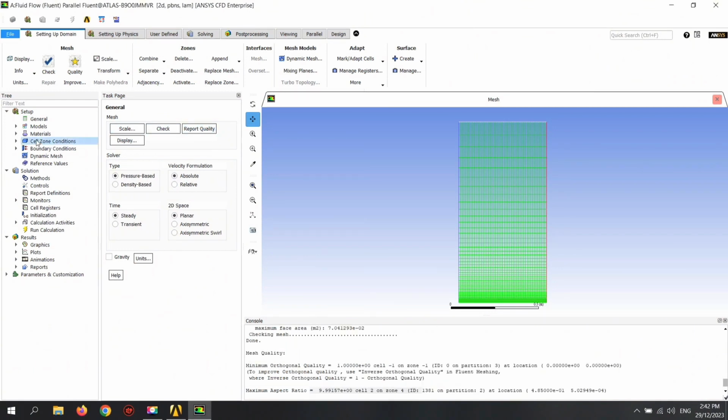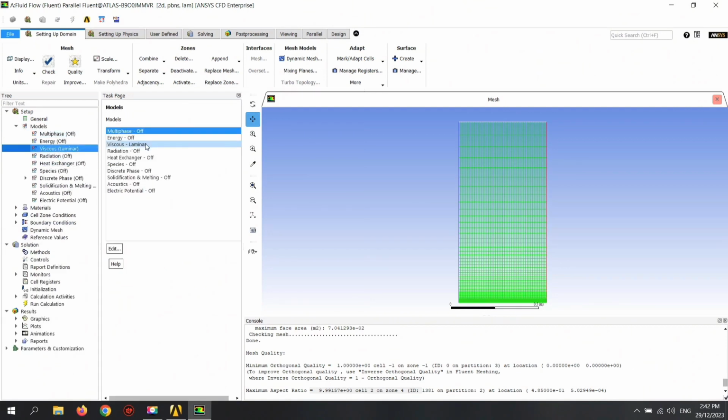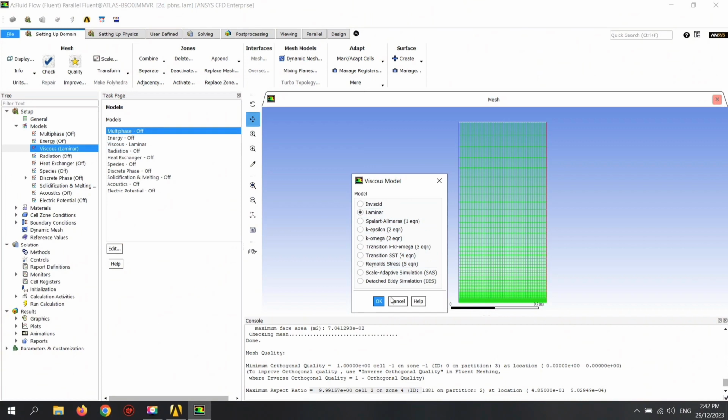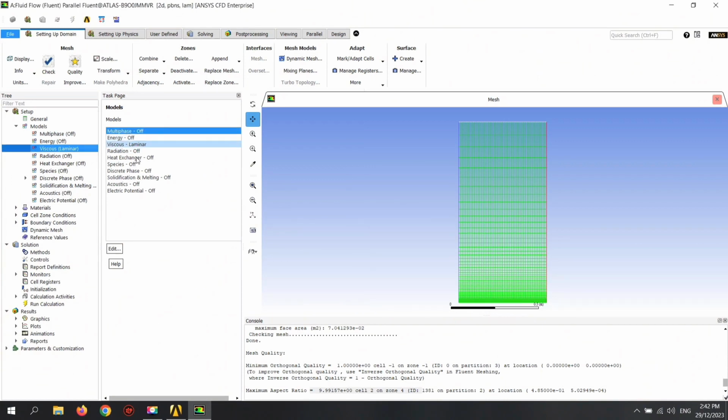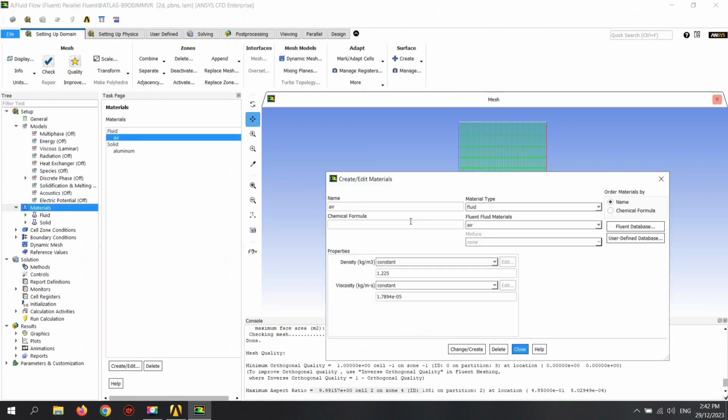And this is our symmetry for the second plate, the same dimension as well. Nothing has changed except for the airflow, which is 2.5. Everything is exactly the same as the previous plate. It's laminar, the air density changed to 1, and the viscosity changed to 0.0001.